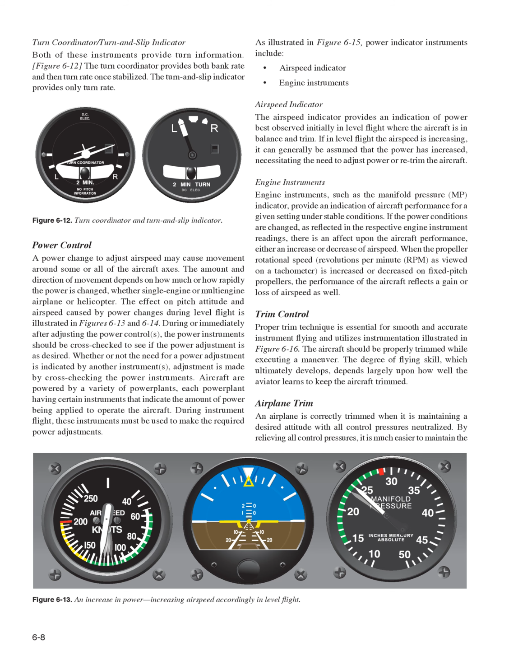Trim control. Proper trim technique is essential for smooth and accurate instrument flying and utilizes instrumentation illustrated in Figure 6.16. The aircraft should be properly trimmed while executing a maneuver. The degree of flying skill, which ultimately develops, depends largely upon how well the aviator learns to keep the aircraft trimmed. Airplane trim. An airplane is correctly trimmed when it is maintaining a desired attitude with all control pressures neutralized. By relieving all control pressures, it is much easier to maintain the